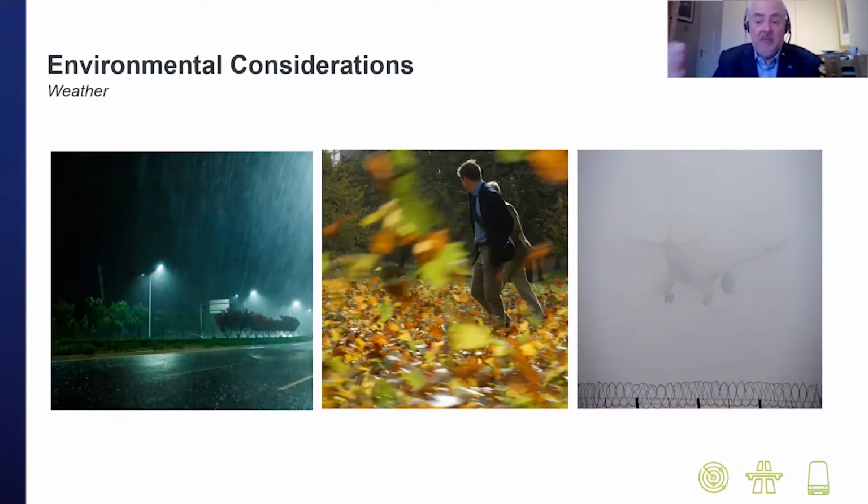So you've got daytime, nighttime, activity due to wildlife, on-site personnel and vehicle movements, for instance, and also seasonal variations due to leaf cover. Foliage presents a particular problem, as it's a barrier to radar energy, so you won't be able to see anything the other side of that vegetation. But it can also create unwanted alarms in very high winds, for instance, as it's moved around. Foliage being blown around might appear as multiple moving targets.